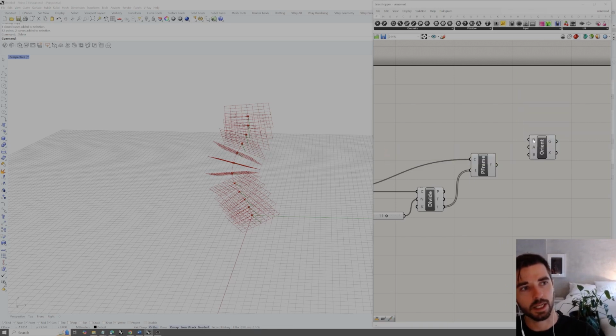It takes in an input of a base geometry, so that's going to be our cross sections, and then an input initial plane. Just like when we copied, we needed to use a reference of the center point, so that initial plane is going to be a reference relative to our cross section, and then a final plane, which we're going to use as all of these perpendicular frames on the curve. So let's go ahead and just start setting this up.